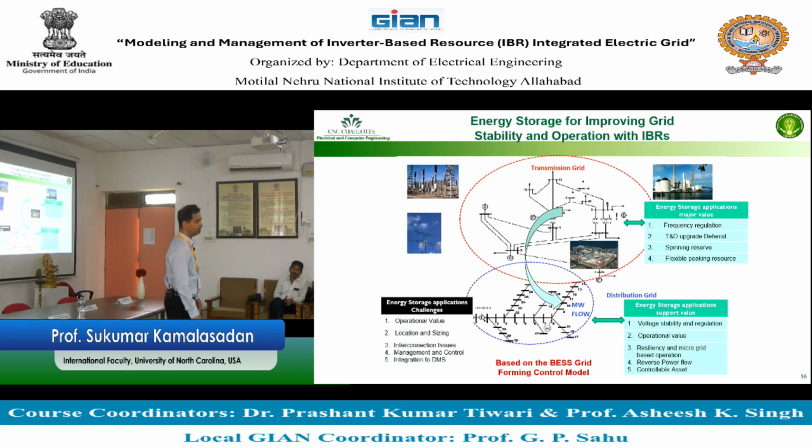Auxiliary services are support services that you do with the device for the utility. One of the auxiliary services is spinning reserve. Spinning reserve means you keep the reserve for the generator and then utilize it. That's an auxiliary service. Why is it called auxiliary? Because that improves the grid stability and reliability. Whatever way it is, it's reactive power improvement, frequency stabilization, angle stabilization, power stabilization. All those things are considered as auxiliary service.